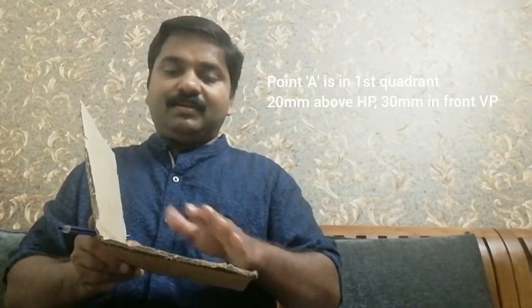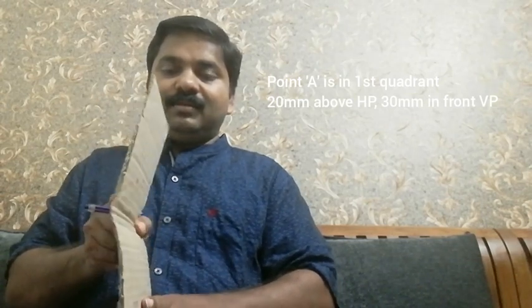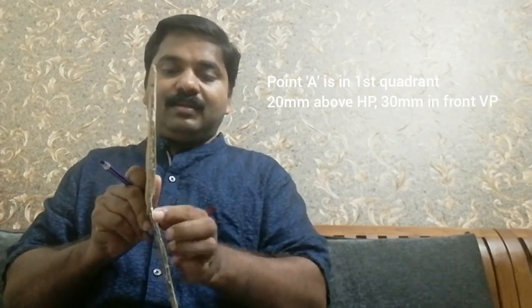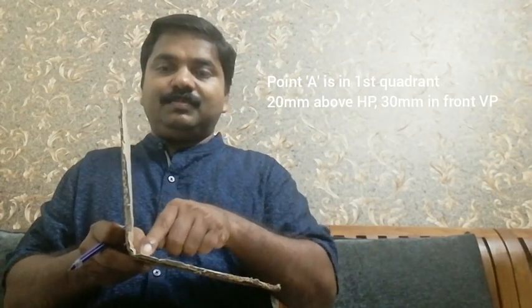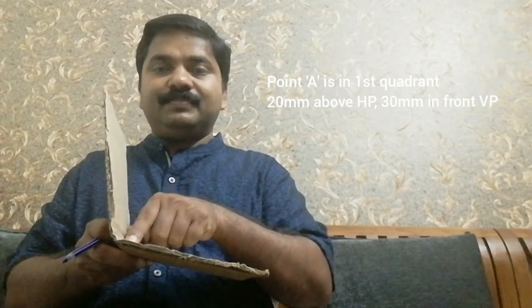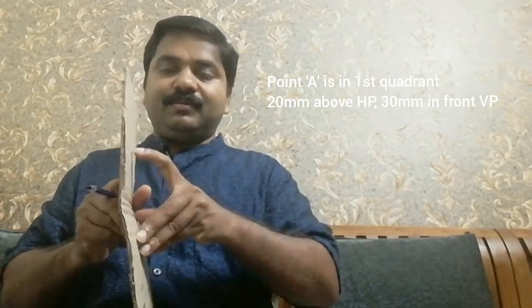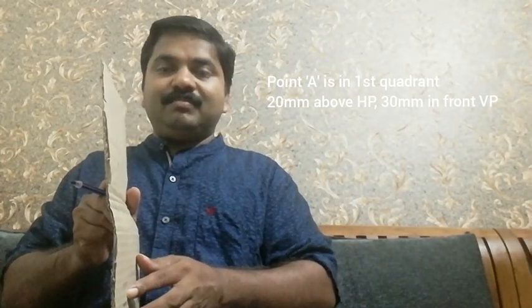The vertical plane will not be rotated. The horizontal plane is rotated in the clockwise direction, so that we will get the front view and top view in a single plane. This is nothing but the intersection of HP and VP. That would be a line, and that is called the XY line. So the front view will be 20 mm above the XY line and the top view will be 30 mm below the XY line.